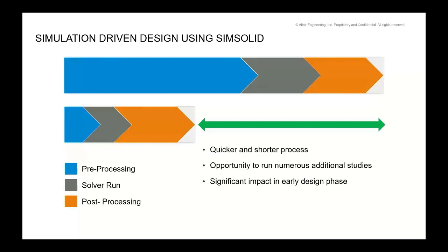The solver itself, because of its new technology and the type of elements it's meshed with in the background, applies high order differential equations on the different parts of your structure in order to calculate the stresses, strains and displacements at those different parts of your CAD. So that's the technology behind it, and that's different to the traditional F equals KU sort of formula that we're looking at.